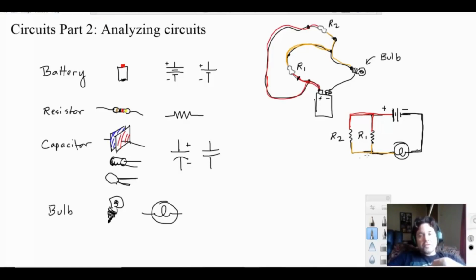But some voltage, right? And then, of course, we know that this one is going to be 0 volts with respect to the ground terminal, because it is the ground terminal, right? So we have two ways to talk about that voltage. You can either say this is 9 volts with respect to the ground terminal, and the orange one is, let's say, 6 volts, right? And then if the orange is at 6 volts, then that means that we're saying 6 volts with respect to the ground terminal of the battery.